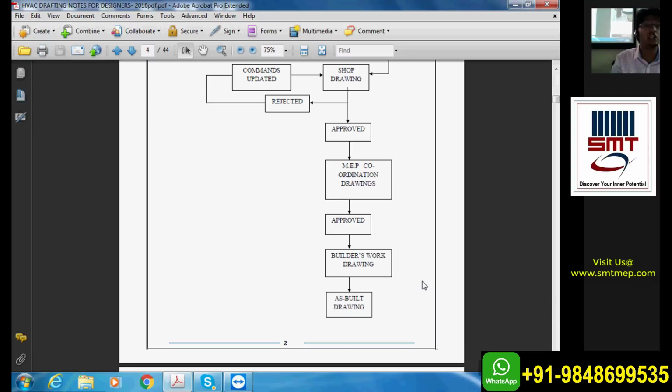If you want to see how those supported layers you used to make the drawing are actually conveying the message of where is what, where is the exhaust, where is the air terminal, where is the actual grill and so on, you can try for your own particular reference. You cannot distribute that to the company on a colorful drawing. It will be disapproved. It has to be approved by the Civil Defense Department only in a monochrome color, which is color 8. Is it clear? So these things are to be remembered and are very, very important.